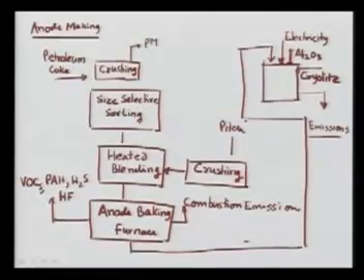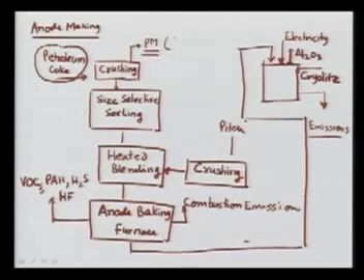What we will discuss here is the flow sheet that you see. I'll go over this flow sheet to explain what anode making really means. As you can see, the anode is made of carbon. So we start with the petroleum coke that we get from the refineries. This is in solid form and is crushed, and the moment you do some crushing, particulate emissions are there. So you can see again the dust emissions, and they need to be controlled either through cyclones or bag filters.